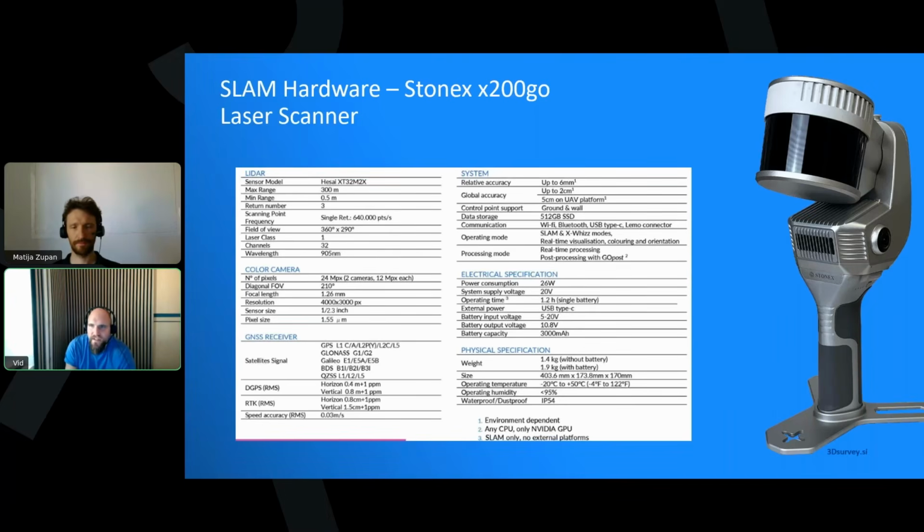One of the benefits of this scanner is that it records 360 panoramas, which can help with the creation of 3D models, because you will later see that we also get those panoramas. If you're not sure how to connect the walls, you can move inside the 360 panorama and see better how the room was composed. Those with a good eye may see that this one doesn't have the RTK antenna attached, but that's optional, screenshot only. When we went out, we mounted the RTK antenna onto it and connected it to our N-trip network.